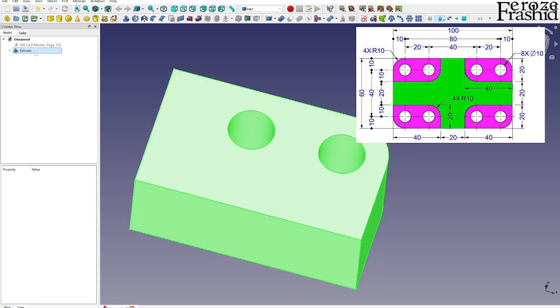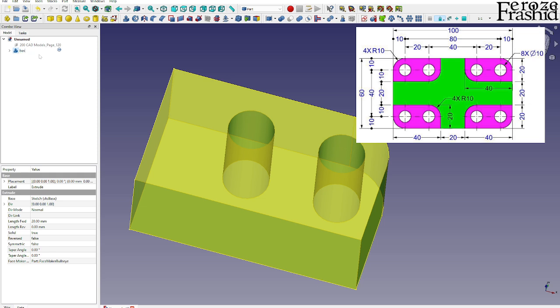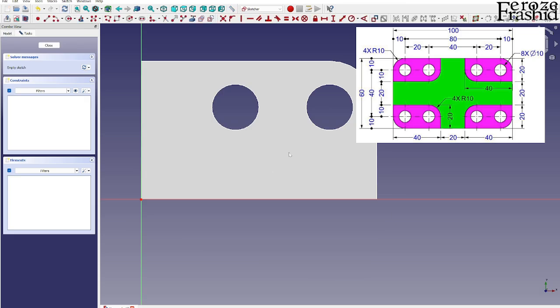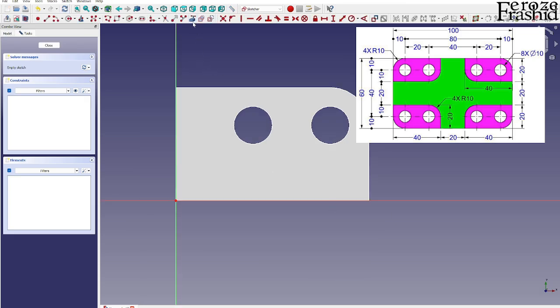So that is our first option. Now I want to rename that first. So this is the base. I want to draw another sketch on top of it, which is 20 millimeters above the XY plane. So let's offset it at 20 and keep it on the XY plane. I will be using these corners and this hole as my references, and then keep drawing the sketch.